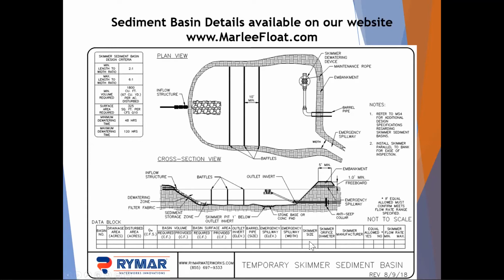And here's the important parts here: the skimmer size, skimmer orifice diameter. Most manufacturers have different orifices available for different skimmer sizes. The skimmer manufacturer, you can go ahead and specify a brand that you based your sizing upon. Is an equal allowed? Yes or no? Now, most of the time that is going to be yes. There are some instances where you may say no. You may have a quantity control requirement, and it may be very important that you have a very precise flow rate to meet that. But in most cases, that's going to be a yes.